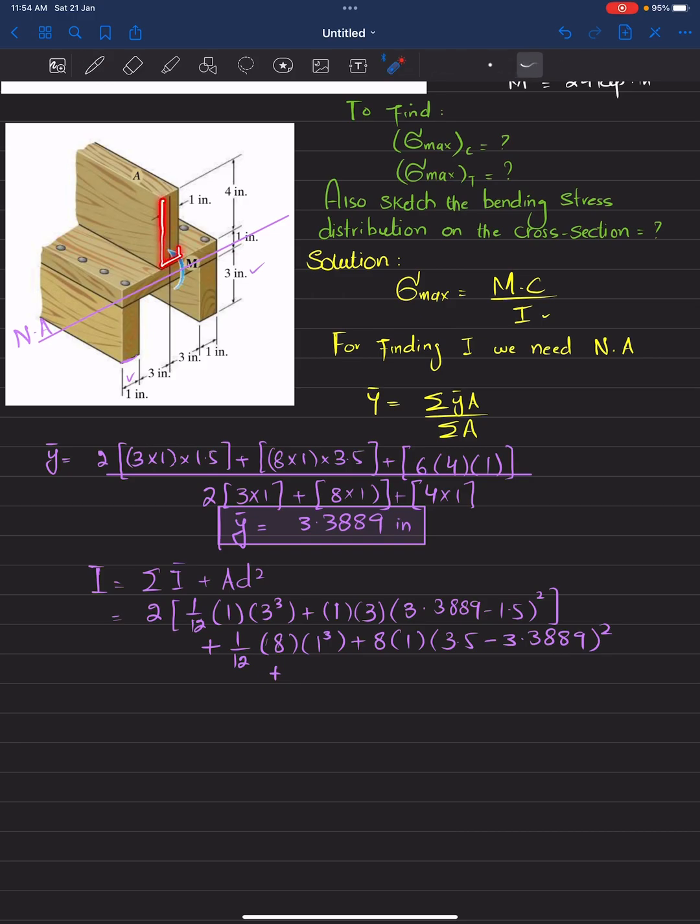So this is the moment of inertia. Its width is 1 and height is 4. So 1 over 12 times 1 into 4 cube, plus this area, which is 4 into 1, and its distance, if you subtract the half of this, will be at a distance of 2 from the top as well as from this portion, 2. So 2, and this total height is now 6.